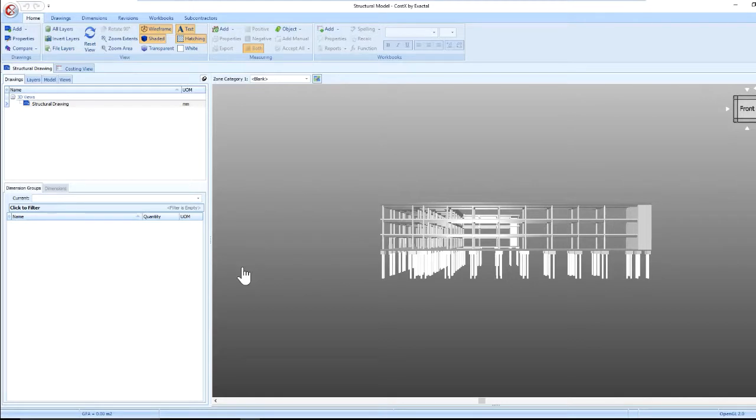Another way that we can get quantities from the BIM file is to use the model maps function. This allows users to determine what specific data will be extracted. For IFCs, we'd use the model maps function over the BIM templates, and some prefer to use model maps for all their BIM file types.